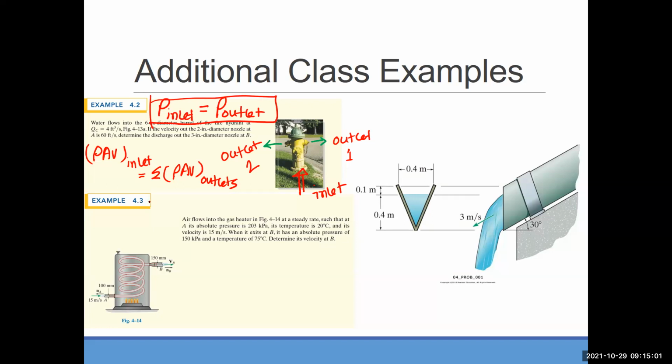Now for 4.3, what is the fluid type, gas or liquid? 4.3, it's the gas, it's the airflow. So some air is entering through this way, that is the inlet, and that is going out through that way, so that is the outlet. And inside that, the heat energy is applied here, like the heat obviously will change the density of the air because that will increase the temperature. Now you have one inlet, one outlet, so you can write down rho AV in, rho AV out.